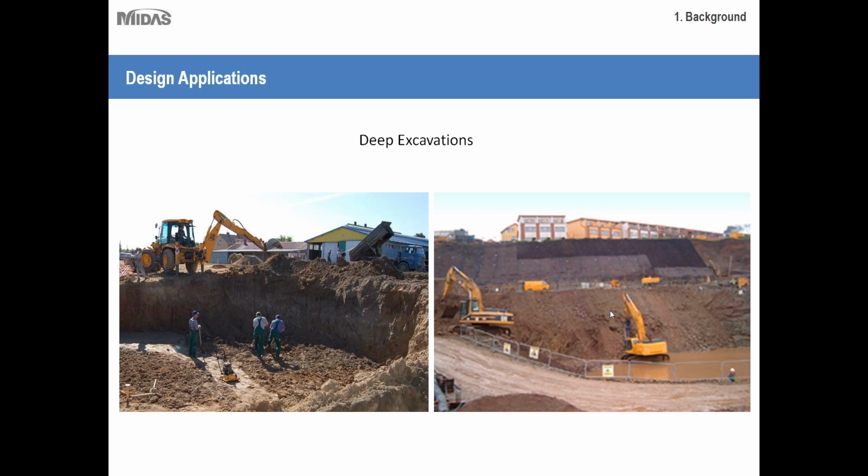The reason this is done is that it's not really logical or very safe to have the excavation dug in at a 90-degree angle. It'd be very dangerous. And if that were to fail, there'd be large amounts of soil falling, which would take a long time to fix or clean up.